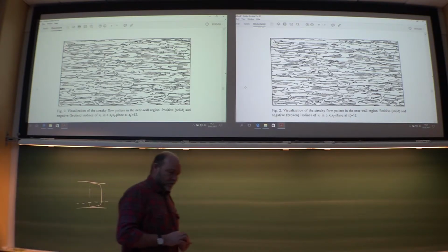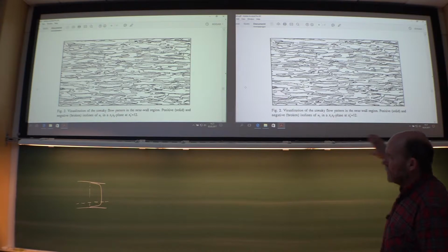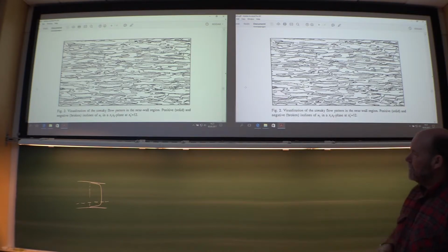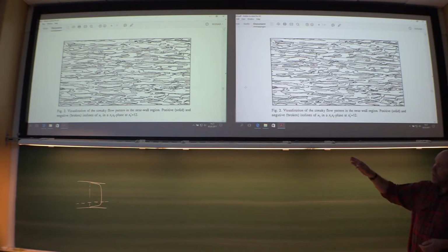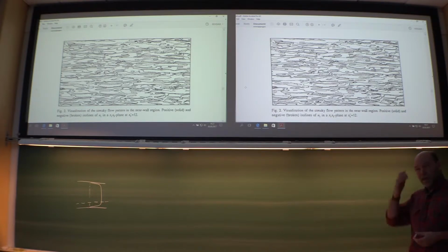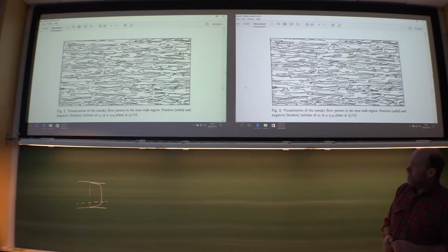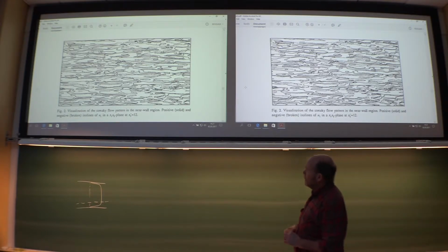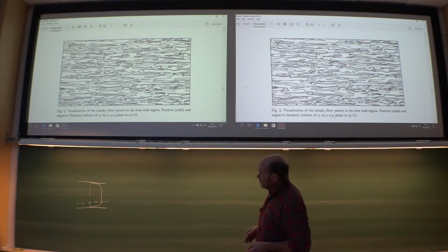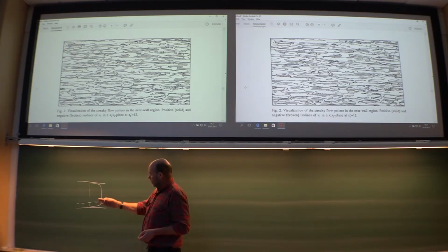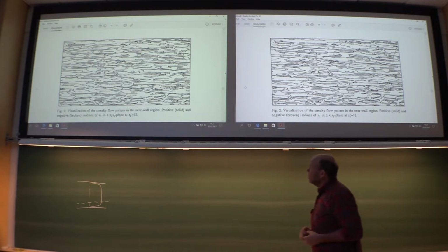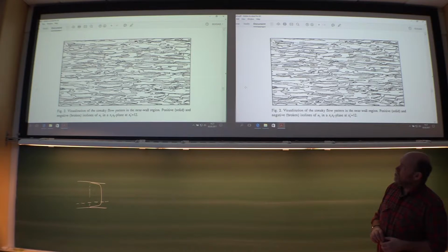If you look at the structure, first of all, it's quite streaky. It's elongated in the streamwise direction. So you have these turbulent streaks close to a wall, and they can be pretty long. This is the entire domain. And I believe my domain was some 4,000 plus units or so in the streamwise direction. So you see they can be pretty long. In the spanwise direction, here in and out of the paper plane, I didn't have that many units, I think around 2,000 or so.